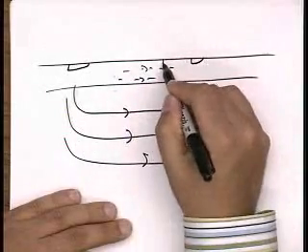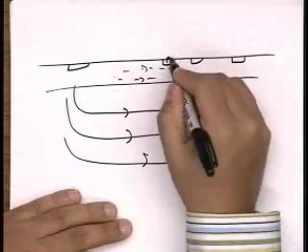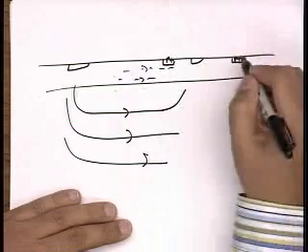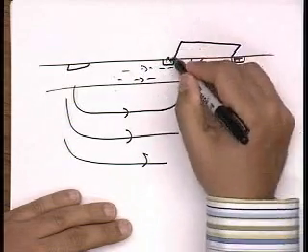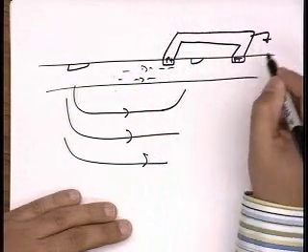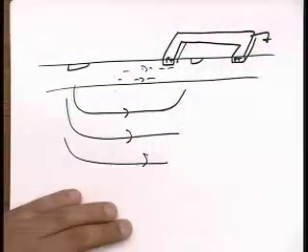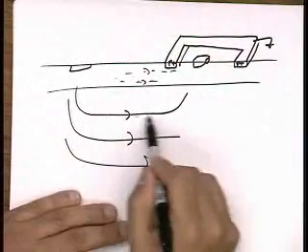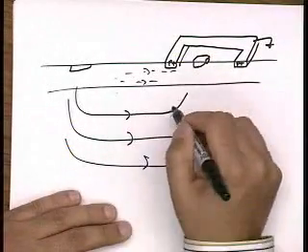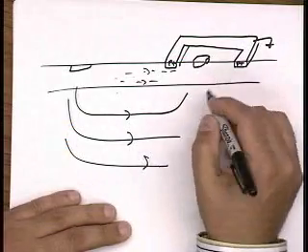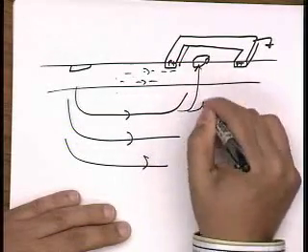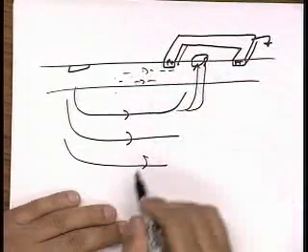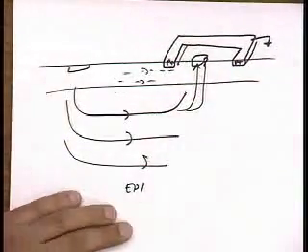And if I put this ring now around my device, so this P plus ring, and I ground it, and this is the contact that I'm trying to protect, the problem is the current's going under. And so it has no problem going under that ring of so-called protection and just reaching my circuit, right? So for an epi substrate, the guard ring is not going to work.